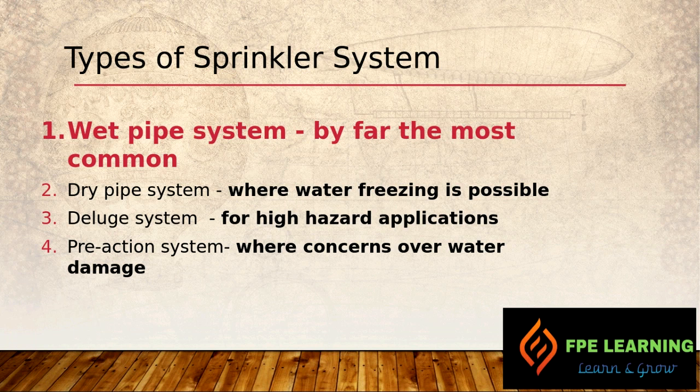But a dry pipe system is a little bit costly and also requires higher maintenance. We can also use a wet pipe system along with antifreeze solutions, right? Normally, if you put antifreeze solutions, something like glycol, into the water, it can go down to minus 10 or minus 20 degrees Celsius without any freezing. So either we use a wet pipe system with antifreeze solution, or we have a dry pipe system option.